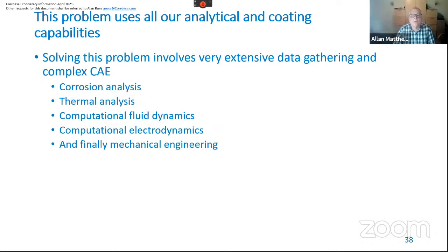I could kind of argue that hardness, if you're trying to emulate cadmium, for example, that performs very well because it's very ductile. Yep. And self-repairs. So in a way, from your zinc nickel, you probably want something that has the ductile characteristics of cadmium, perhaps. I don't know. Yeah, well, that's certainly a very good point, which is why zinc nickel. I mean, cad is great on bolts precisely because you can screw them in and it just gives. But zinc nickel can't do that. And so you immediately say, "Oh, does that mean there's a fatigue problem? Does that mean that we could easily get stress corrosion cracking?"